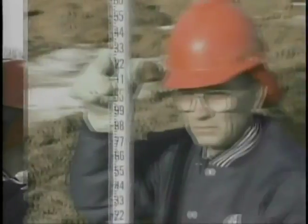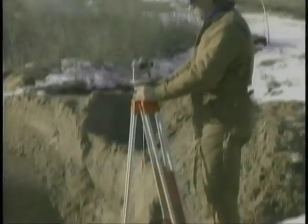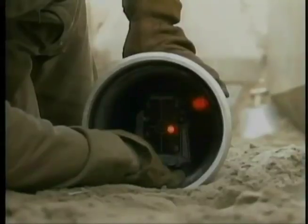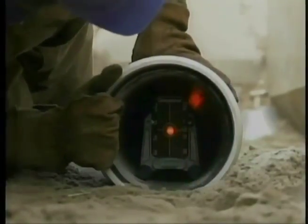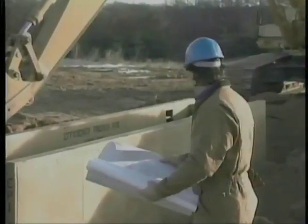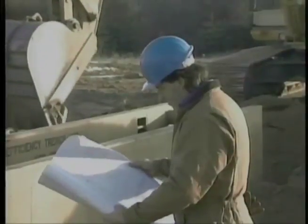Since sanitary sewer systems carry liquids and solids, accuracy requirements are more stringent than for other utility installations. Accuracy requirements of 1/100th to 3/100ths of a foot per length of pipe are not uncommon. Since direction changes only occur at a manhole, a laser is one of the most efficient ways to control line and grade. Always refer to the local plumbing codes to determine the actual requirements in the area of installation.